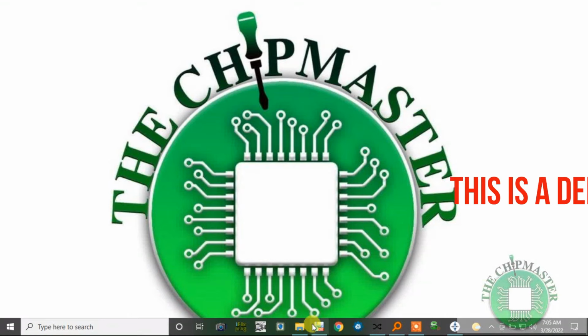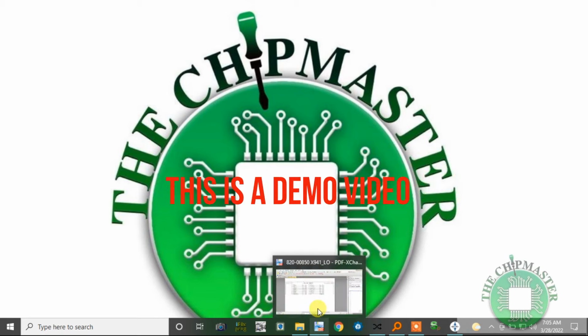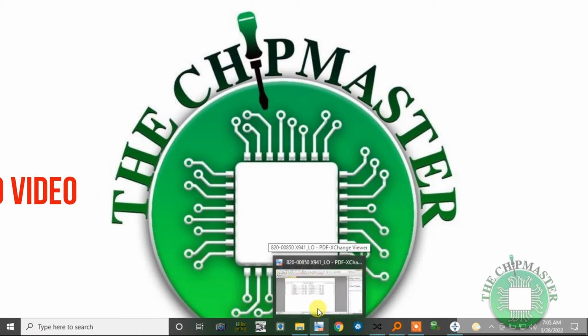Alright, so welcome back, and this is the Chipmaster, and in this class we're going to discuss the Apple A1989, the Type C boot process, the boot sequence, and we're going to touch a little bit on the Type C architecture and other things.